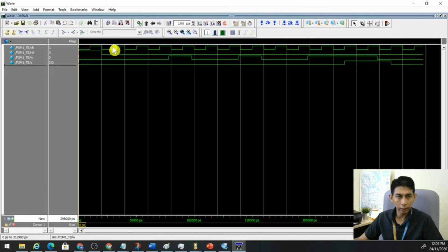So one clock cycle means one measurement, right? For example, in this measurement, W goes to 1, and we see that after one clock cycle, in another measurement, the W here has gone down to 0 already, so Z will never go high.